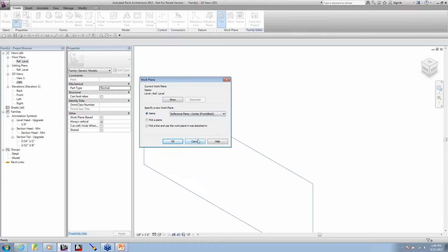Hey, Brian, this is a good time to jump in here. We do have a question regarding reference plane. Sure. Does a reference plane have an inside and outside? An inside and an outside. I'm trying to think. It was like SketchUp. No, there's not an inside-outside. There is a positive direction and a negative direction when you're drawing with them. There is no inside and outside within it. So I don't know if that answers your question. There's just a direction that we can draw, either a positive direction or negative direction, within that plane itself when we're assigning it volumes and stuff. So hopefully, Dan, that answers your question.